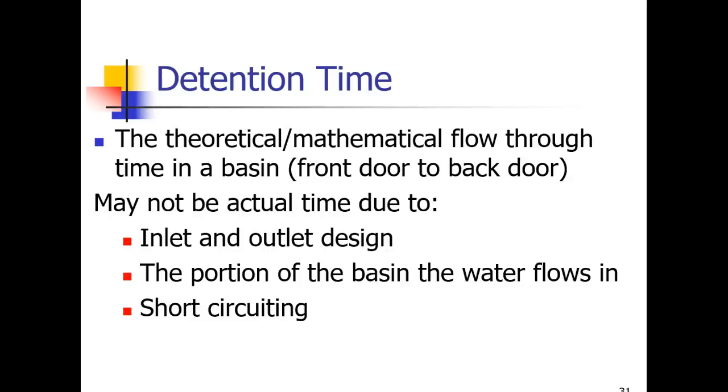The detention time. The theoretical mathematical flow-through time in a basin, front door to back door. How long does it take to go through that basin? It may not be the actual time due to the inlet and the outlet design, the portion of the basin the water flows in, and again, this short circuiting. Short circuiting is a real issue with water because, again, it's always going to take that point of least resistance, and many different things can create short circuits in your water system, in your water treatment plant.